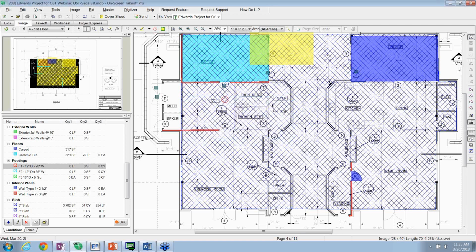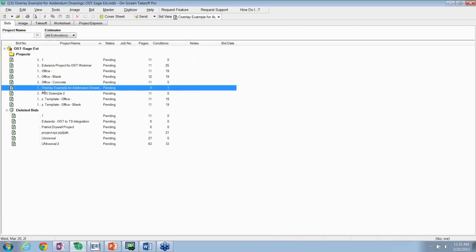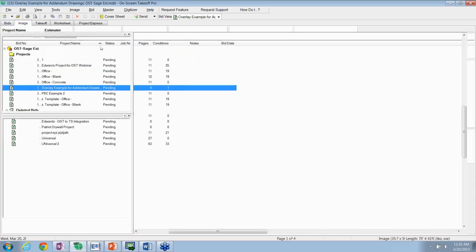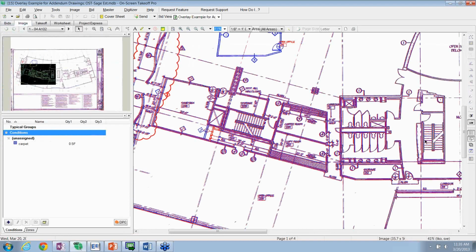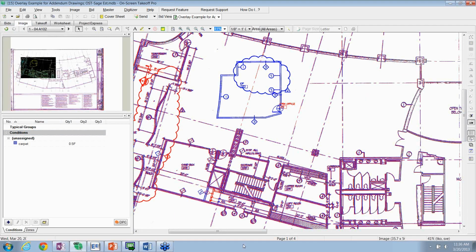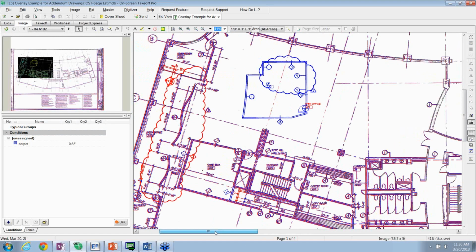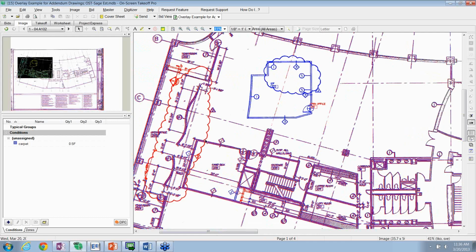So, at any rate, the other thing that this does too, above and beyond just doing quantity takeoff and communicating what you've done here, it also has an overlay capability. And the overlay allows you to put one set of drawings on top of the other and physically show you what's changed. So if you notice here, blue was existing, red is something's changed. And if you notice here, the idea is to really flesh out those clouds. So if I took a previous set of drawings and overlaid that on a revised set, this instantly gives you the red, blue, and gray remains unchanged.